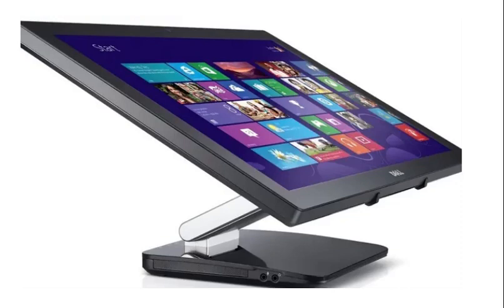IR, infrared, touch screen. IR, infrared, type touch screen monitors do not overlay the display with an additional screen or screen sandwich. Instead, infrared monitors use IR emitters and receivers to create an invisible grid of light beams across the screen. This ensures the best possible image quality. When an object interrupts the invisible infrared light beam, the sensors are able to locate the touch point. The X and Y coordinates are then sent to the controller.